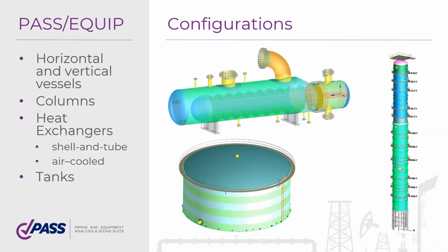So what kind of analysis can we do with this application? You know that most of these pressure vessels can be analyzed by formulas. If you look at any codes for stress analysis of this type of vessels, they include a lot of formulas developed from shell theory. And of course, we have all these formulas, and we can quickly analyze any type of vessel according to them. But when it's necessary, we also use finite element methods. For example, when we deliver any configuration of PAS Equip, by default, we also deliver PAS Nozzle FEM for finite element analysis of nozzles and shell junctions.